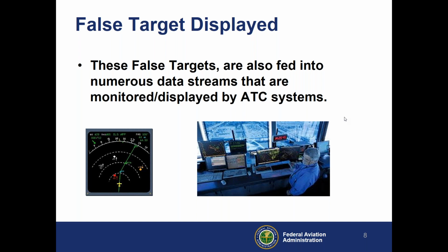So the bottom line is that now, while maybe back in the early days, if you were radiating a signal, free ramp testing with no couplers or such, you had to worry about interfering with an airplane that was flying over you that just had the right position to where you were giving them a false TCAS alert or something like that. And possibly if you were close enough to a radar site, tower controlled airport or something like that, you might show up on their display.